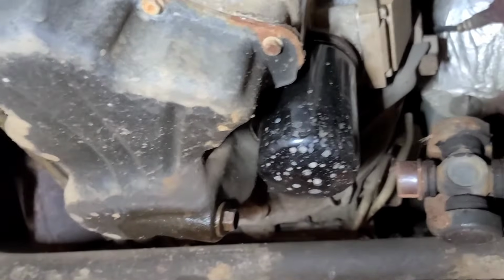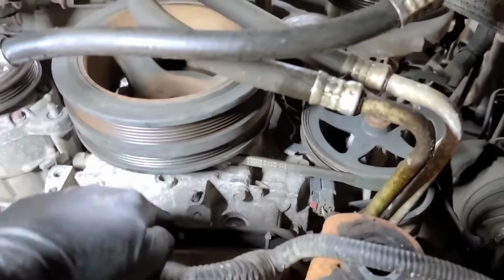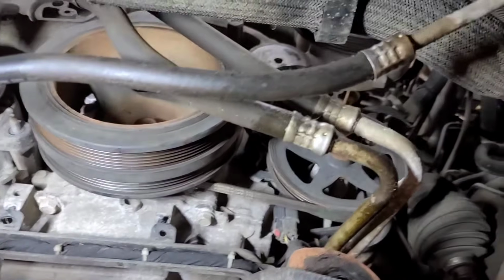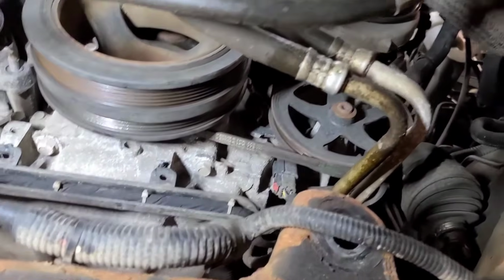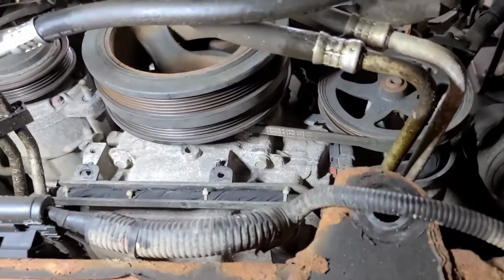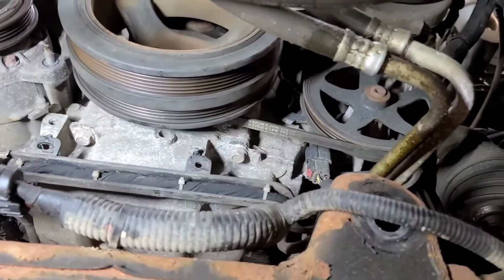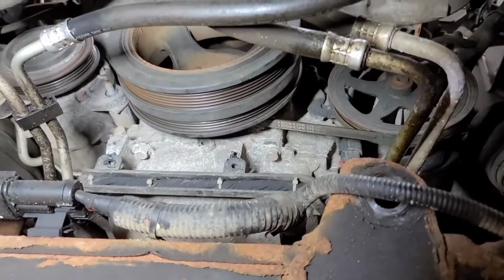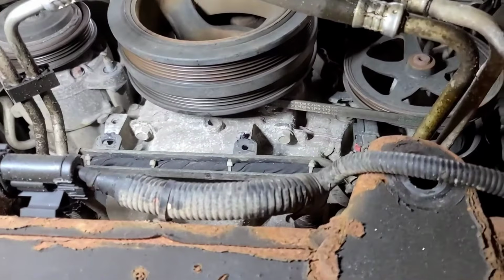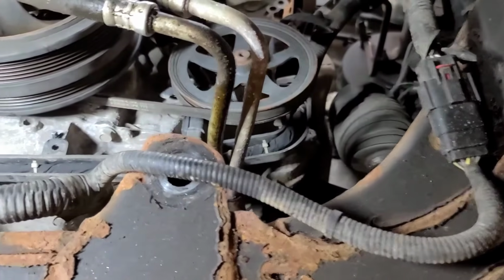Oh well. It was easy, anybody could do it. So unclip the wiring harness from the front, and we're ready to let it down and take the dipstick tube out because that's going to be a problem. And might as well take the harmonic balancer off and finish disassembly. I haven't drained the coolant yet because I haven't opened the cooling system. I didn't want coolant dripping on me while I was underneath the truck. So we still have that to do.